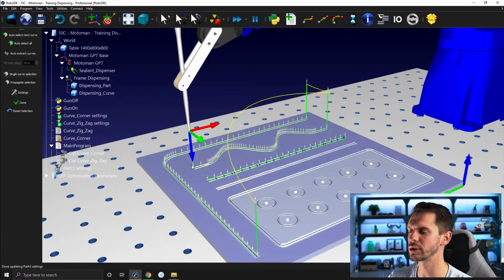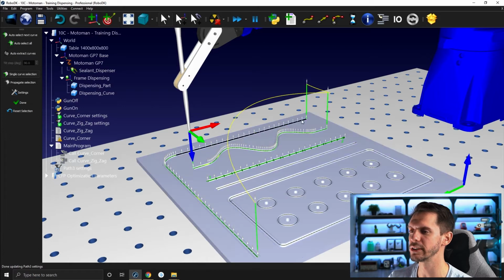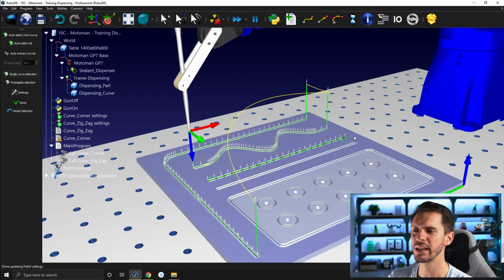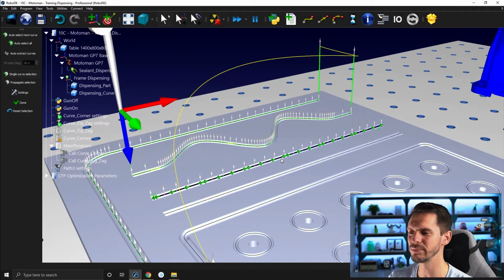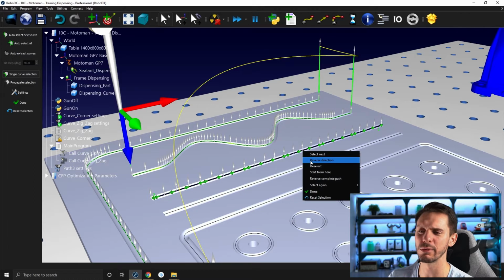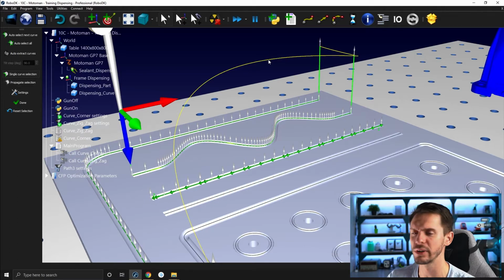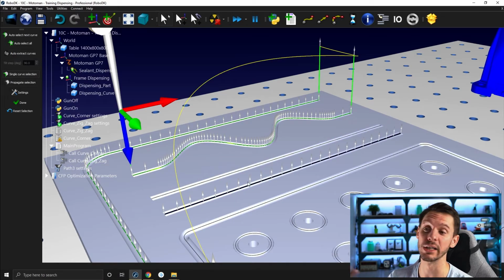And let's say we'll start from this here because we'll go this way here, from here to here. But I want to go back from here to here. If I reselect the curve again, the only thing that happens is it flips the sense. I personally always do right-click, reverse direction, but that's more a habit than anything else. So if you re-click on the curve, it will flip the sense, and if you click another time, it will deselect it.